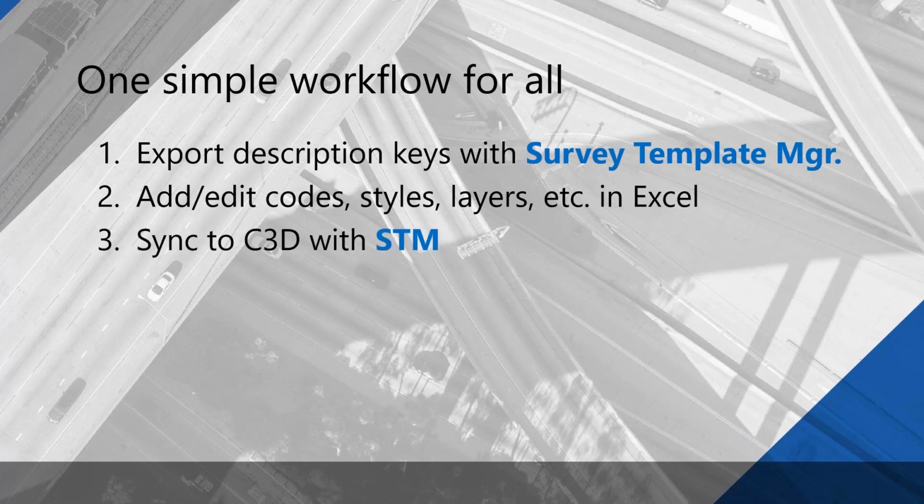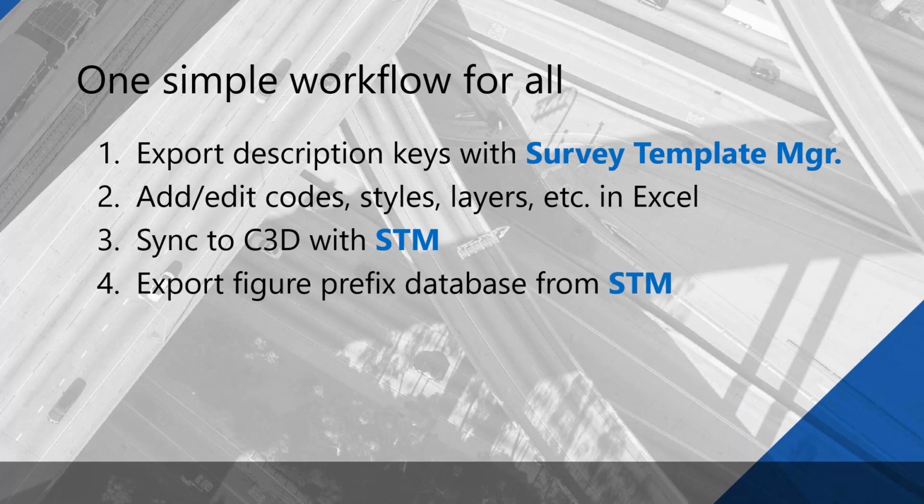Once you've done that work in Excel, you sync back to Civil 3D with the Survey Template Manager, and all those changes within Excel will push to either creating a new standard or updating the existing one based on what you changed in the Excel spreadsheet. And we can do the same for the figure prefix database with the Survey Template Manager.